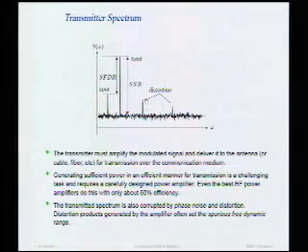In fact, there's usually a spectral mask that we have to satisfy, which is again set by the standard of communication that we're using. So, of course, I can use filtering to get rid of these harmonics, right? That's not too bad. Build a little low-pass filter, and you get rid of that.